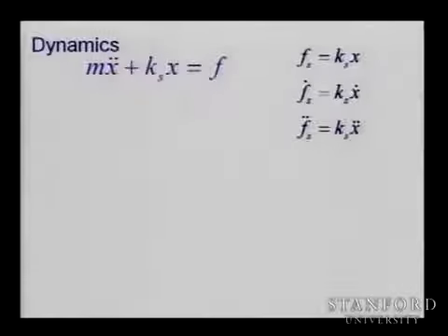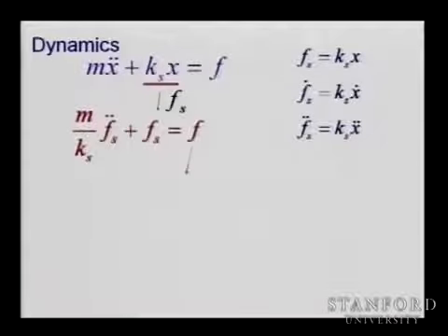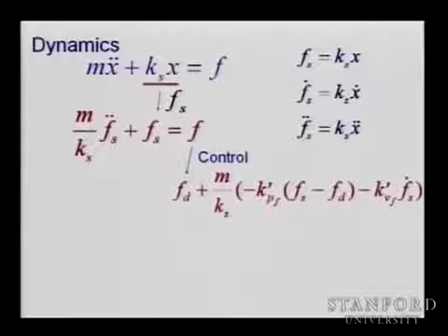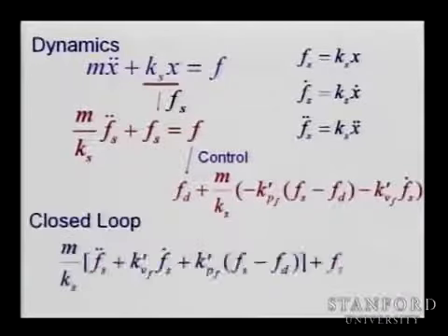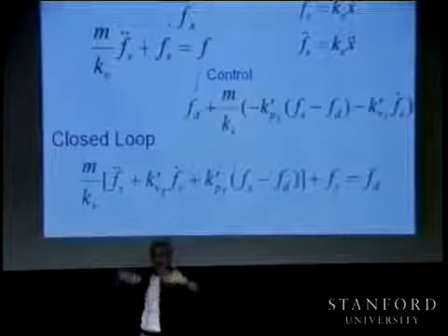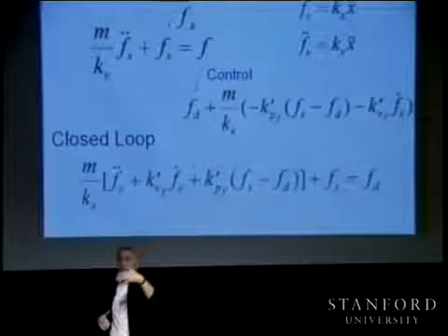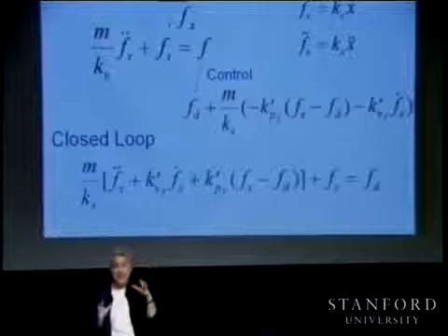So if you think about how we can do this, basically you have the relation between forces and displacement. You take the derivatives, and then you design a controller like this with a proportional term, derivative term, and then you are able to have a closed loop that minimizes this. And the response now is in force space for the robot. I'm not expecting you to understand all these details, but essentially force control is going to be a very, very important aspect of robot control.